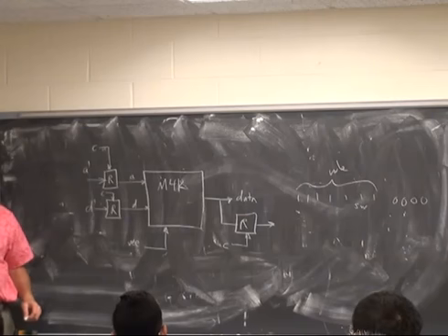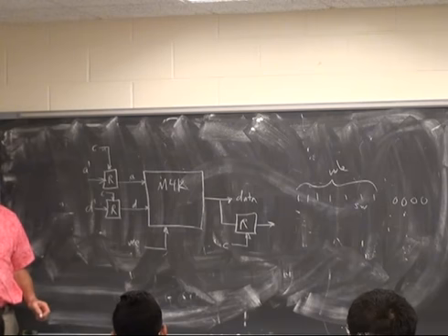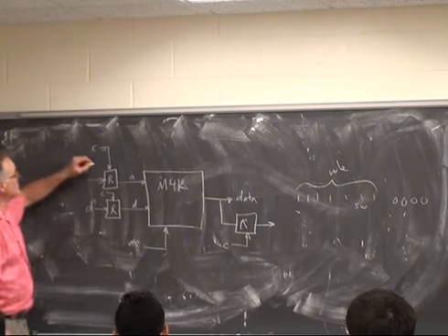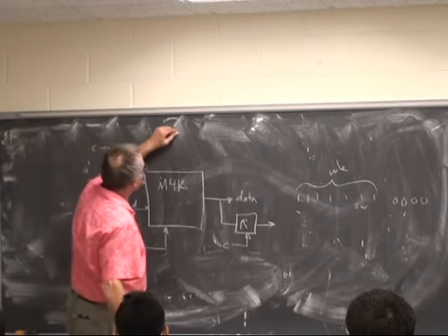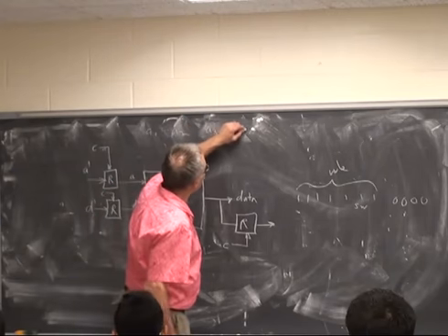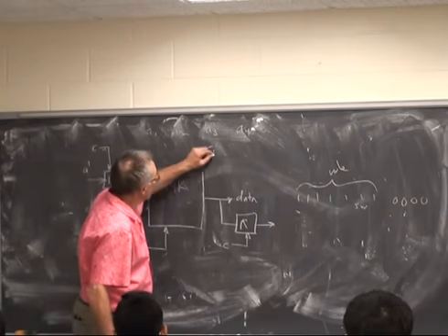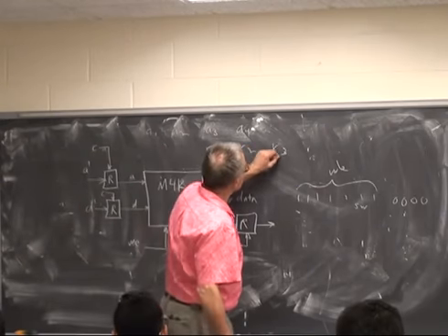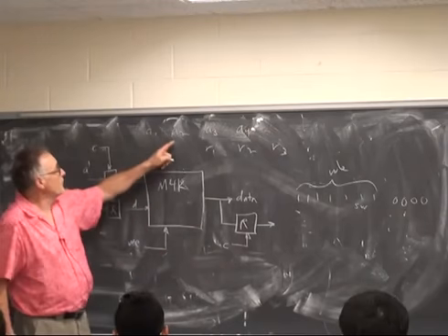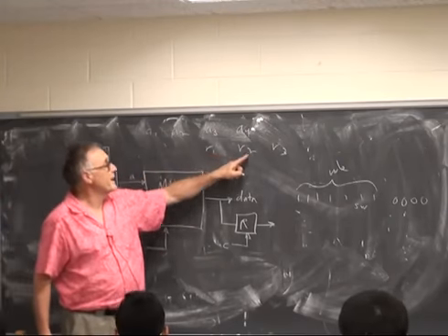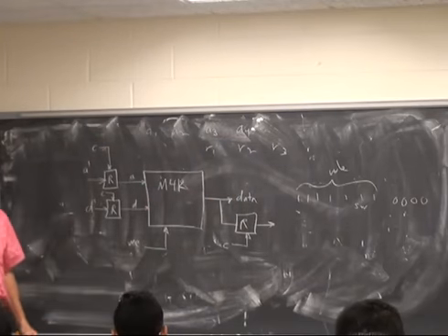Now, all this can be pipelined. So you can do an average of 1 read per cycle, but you have to delay the interpretation of the output 2 cycles from when you set the address. So you can set address 1, address 2, address 3, address 4, and then read result 1, result 2, result 3. So after you fill the pipeline for 2 cycles, you can get 1 readout for every address you put in on every cycle.